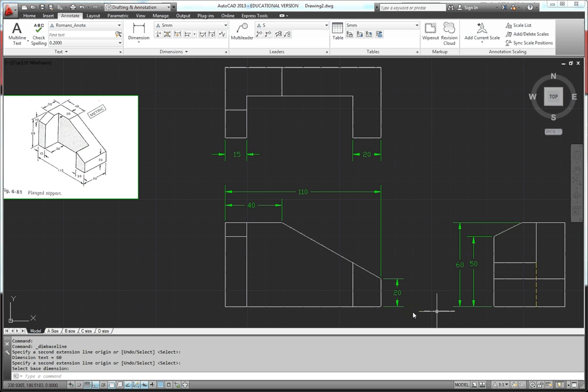So now I've found this first edge, which I could have shown here or here. I felt that it's better shown in the front view. Now this edge, I don't have to dimension the height for that, and the reason for that is that I'm not going to ask the person making this part to make sure that they have this so high. I've asked them that this be 20 wide and it just goes straight up into this slope. So just wherever it goes is where it goes, and I can't ask them any more than that. So we don't need a dimension here, but we have found this edge, and then we found the overall height.